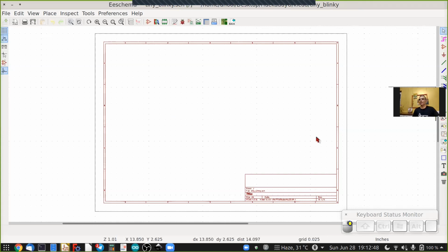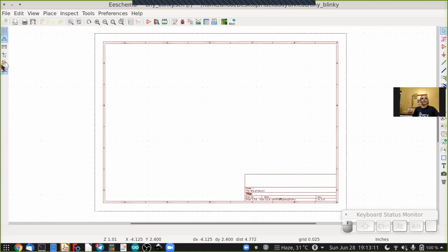There are three toolbars that you essentially use. On the left are a couple of system parameters that you set. For example, the first one either shows or hides the grid dots. You need to set the measurement units that you'll be using. With the schematic editor, it really is irrelevant to use metric or imperial. You can have long or short cursor shapes. You can show hidden pins. So that's the toolbar on the left.